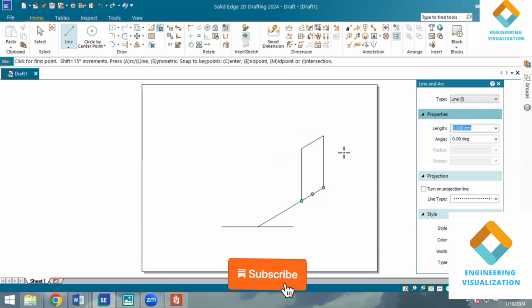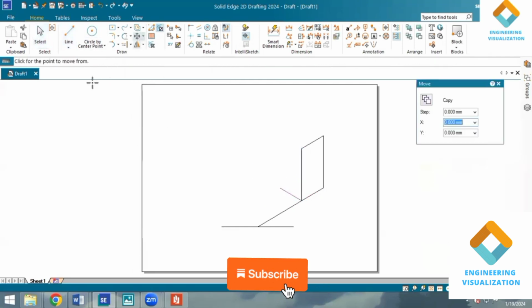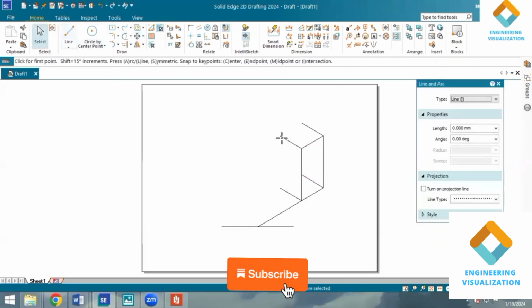Okay, now we have to give the width here. So width of 30 mm at an angle of 150 degree. Okay, so the same line I'm going to transfer using the move command, create a copy, then place it like this, so it will reduce your effort. Okay, now complete it, so the rectangle block will be over.